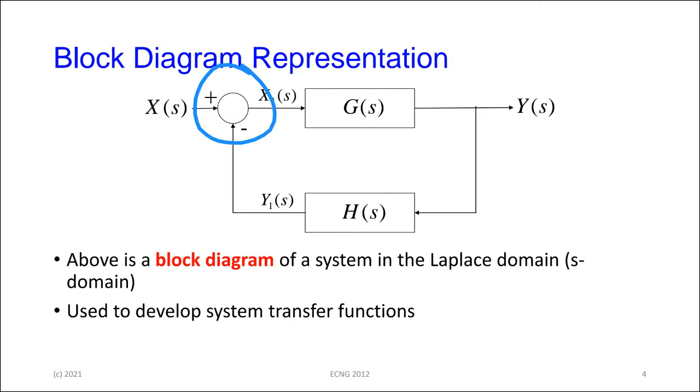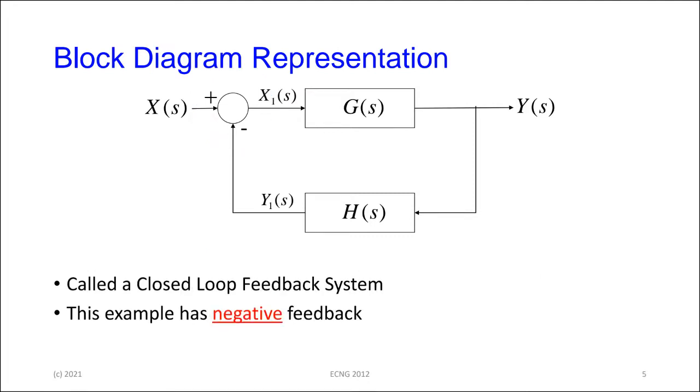That's an op-amp. It's an op-amp circuit where you have multiple inputs coming in, for instance, on the inverting input, and the op-amp sums whatever comes in. So you can sum and invert, or you can invert first and then sum, however you want it. So this particular one is an example, as we said, of negative feedback, because whatever is taken from the output is processed a little bit, but here it is subtracted from the input. So we have an input here, and we are subtracting some part of the output from it.